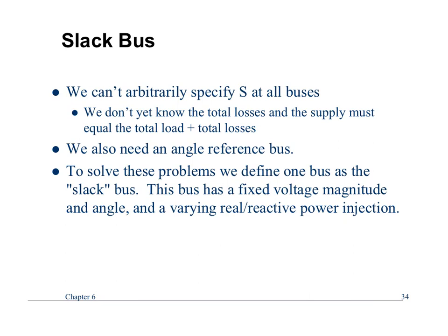The first thing is, what are the 2 equations, or 1 equation or no equations we write? So for example, is it a slack bus? Well, that'll tell us how many equations we can write and how many things we need to solve for as well. If it's the other 2 types of buses, it'll say the same thing. So knowing the type of bus will allow you to simplify and actually write equations. And so that's kind of why we have to do this definition.